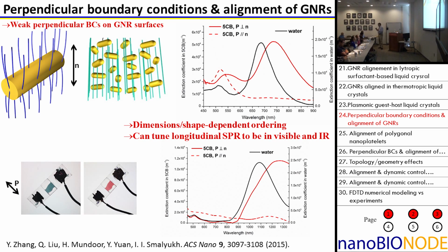Now, we can also orient the particles to be orthogonal to the liquid crystal director, so they will all orient as depicted here, with rod-like particles pointing perpendicular to the director orientation, which we again can switch. And again, by designing the nanoparticles of different lengths and diameters, we can control their properties by changing polarization and applying voltage. And you can see from the example depicted here that the color change can be fairly dramatic, right?